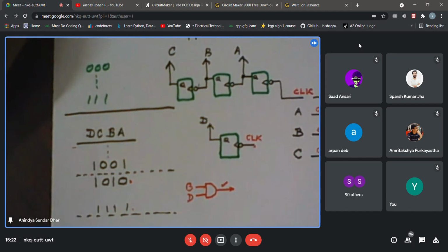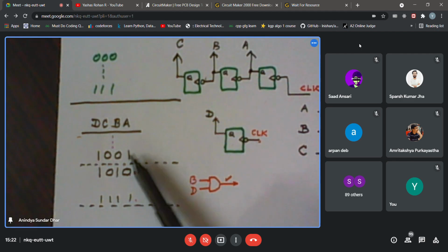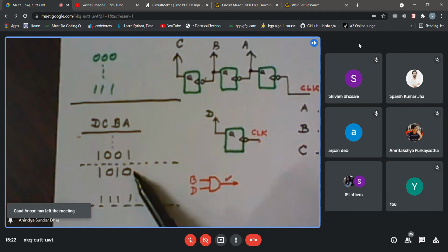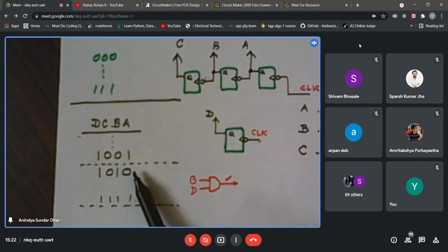Suppose you are using it for a real-time clock, changing it every 1 second or so. You will find that all the states 0 to 9 stay for 1 second, whereas this extra state happens in maybe hundreds of nanoseconds, or even less than a millisecond. So as far as human users are concerned, you do not face any problem. Only if you are using it for some automation could there be some problem. I'm coming to that one, since I've mentioned it, otherwise I'll forget.